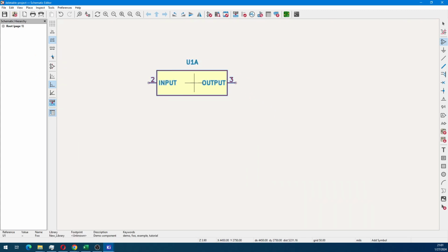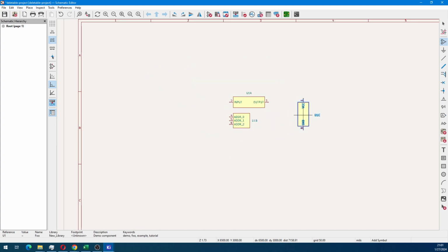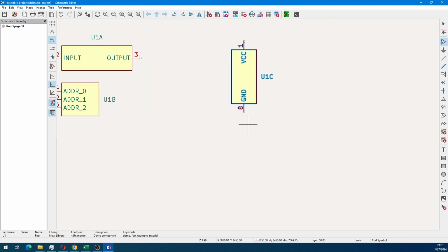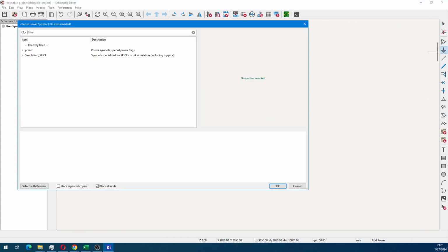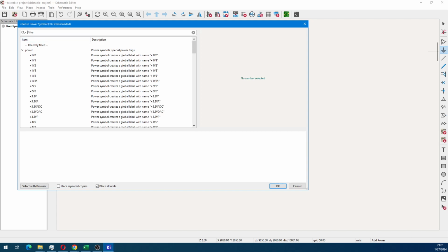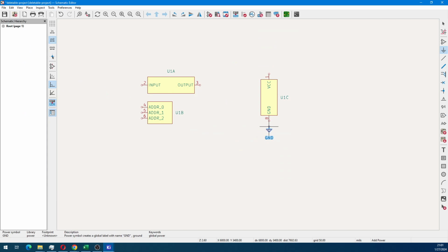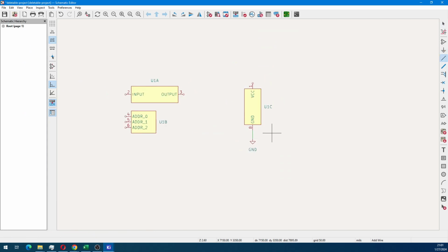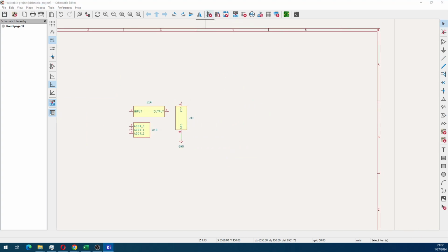And if you click the checkbox at the bottom of that dialog, it makes it a little bit easier to add the units A, B, and C in sequence. That's pretty useful because if you're using somebody else's custom part, you're not necessarily going to know how many units there are, and it would be easy to accidentally miss one. And from here, everything else just works kind of like you would expect it to, just with a normal component that you've added via KiCad.